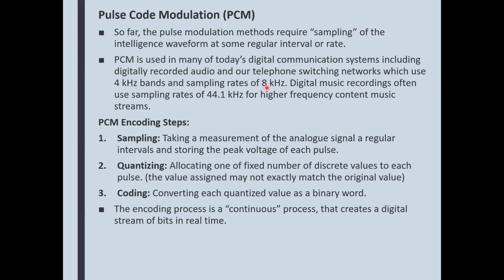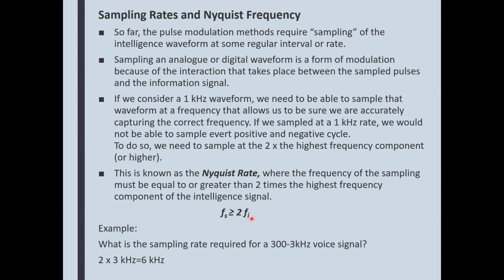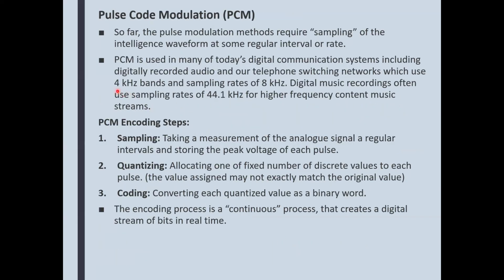So for voice, 3 kilohertz is the highest frequency that we care about. Just to make sure, let's make it 4 kilohertz of bandwidth that we need. That's going to be enough to fit 3 kilohertz in a 4 kilohertz kind of slot, right? And in order to convey that properly, when we do the digital sampling, if we sample at 8 kilohertz, then we're going to have good enough transmission of a voice signal.